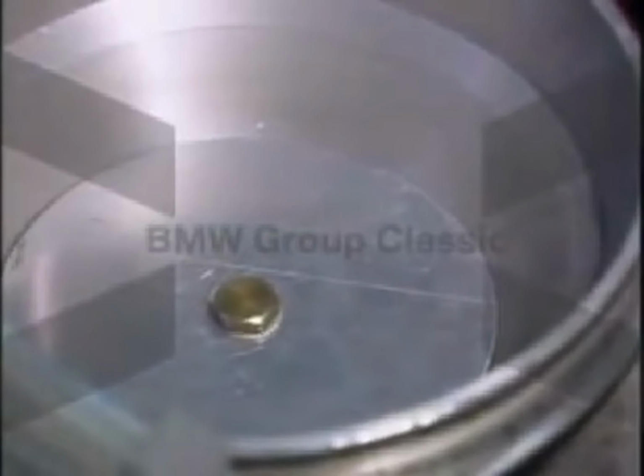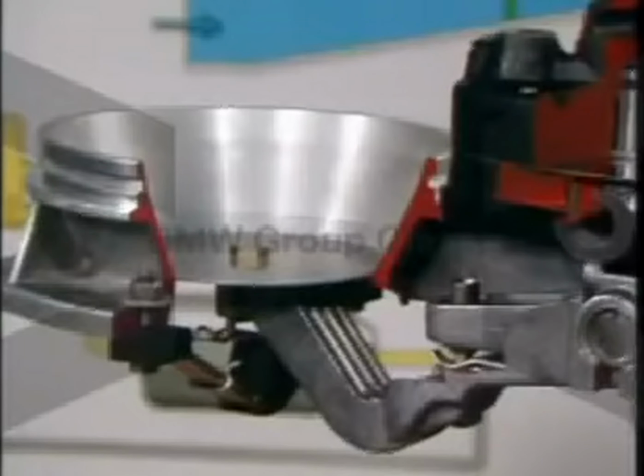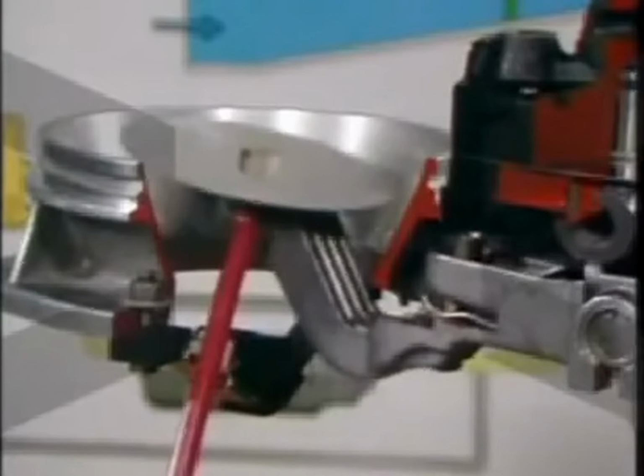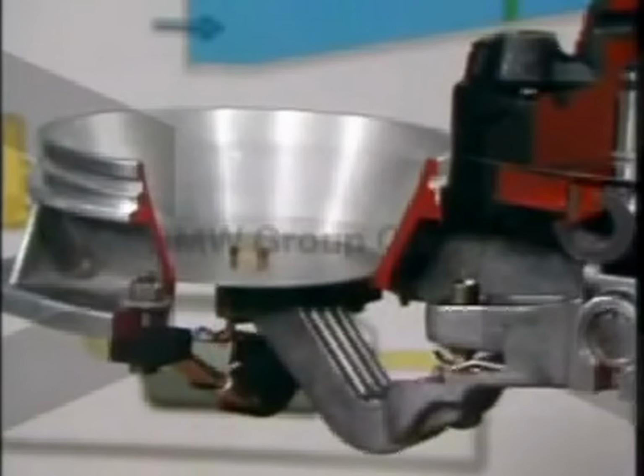After checking the sensor plate positioning, we check the airflow sensor fulcrum for ease of travel. Switch the ignition on for about 5 seconds. After switching off, a residual pressure will have been maintained, causing the control plunger to come to rest on the fulcrum.